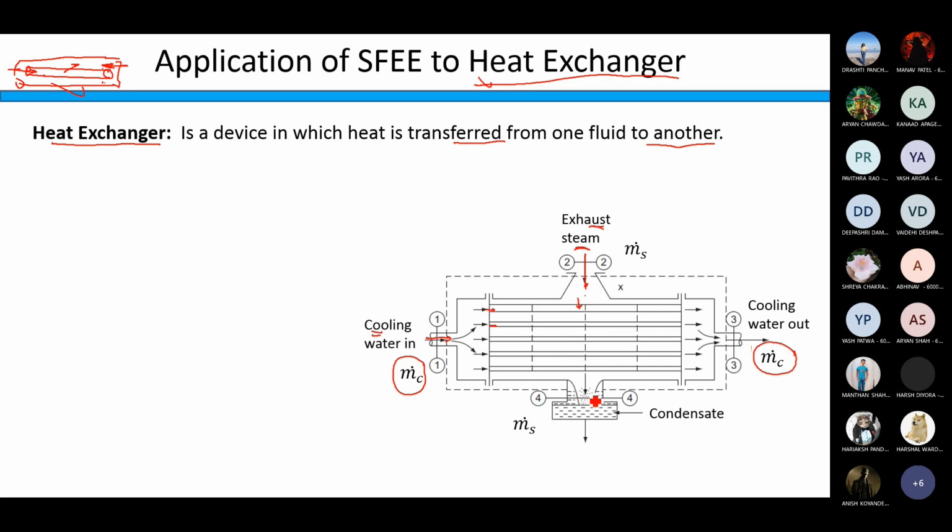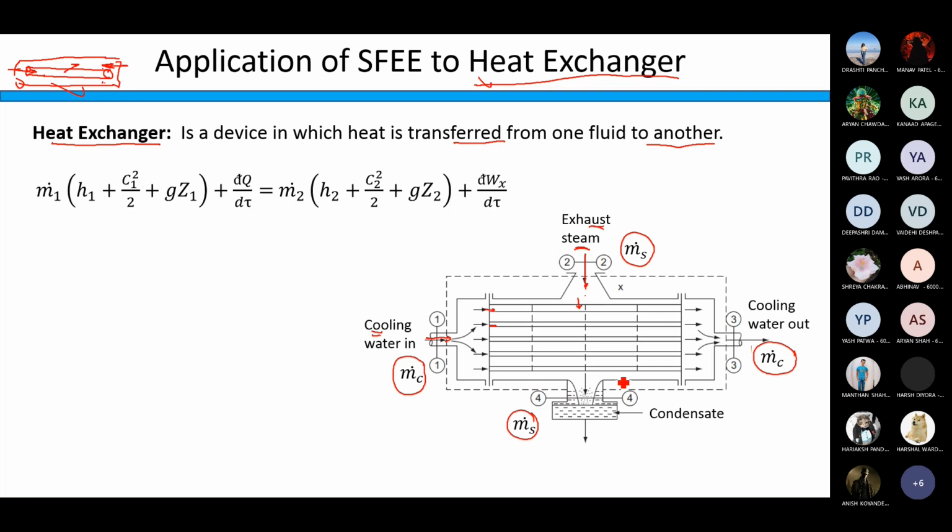will get condensed, and the condensate, or the water, will be collected in this tank and passed on further, right? So this is the mass flow rate of the steam, m dot s, through section 2. It will be the inlet, and here it is the outlet. So this is a simple flow device, we call it a heat exchanger, where there are two fluid streams exchanging heat with each other. Now I am starting with the basic equation 10, and I will try to simplify this same equation.